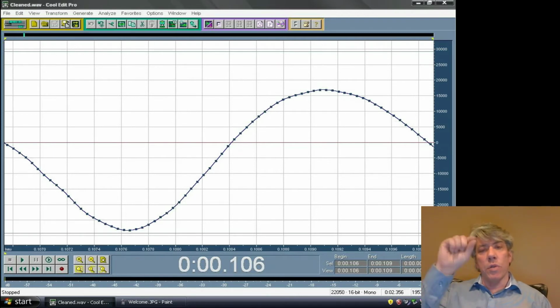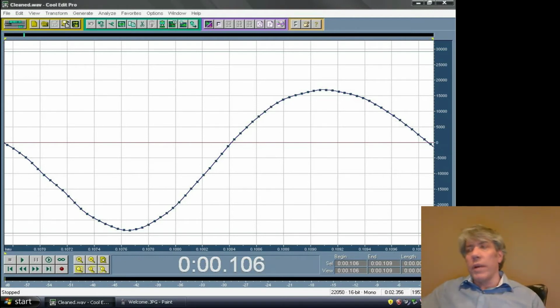So that resolution on the vertical axis does not necessarily have to be 65536 like it is here. 65,000 different temperatures. You might say, well, why would I ever want to measure a temperature up to 65,000 degrees? That's not how resolution works. If you set it up so that your range is from, say, 0 to 2,000 degrees Fahrenheit, you break that range down into 65535 or whatever the resolution is of your system. You break it down into that many steps. So you could sense a temperature change less than a degree in that instance. Okay.